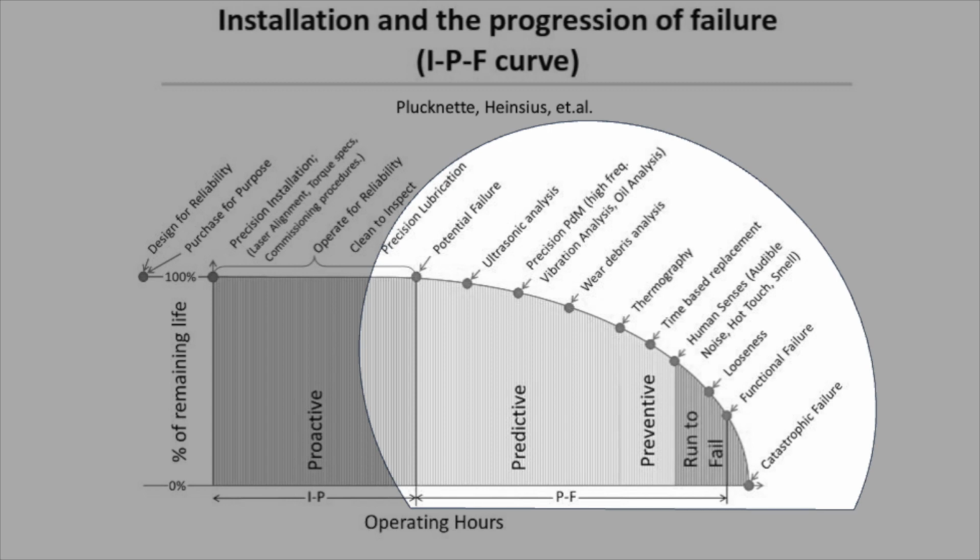The effectiveness of condition monitoring depends on three factors. It must be possible to detect reduced failure resistance for a specific failure mode. It must be possible to define a potential failure condition that can be detected by a specific task. And third, there must be a reasonably consistent age interval between the time of potential failure and the time of functional failure. This is known as the P to F interval. Whenever an on-condition task is applicable, it is the most desirable task, since it is usually the lowest cost alternative.